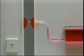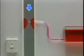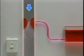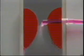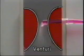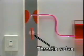Now, let's narrow down the mouth of the tube to speed up the airflow and see what happens when we try it again. As you can see, liquid is atomized, that is, changed into a mist that can be blown out through the pipe. This is basically how a carburetor works. The portion that was made narrower to speed up the airflow is called the venturi. Below the venturi is a throttle valve which controls the air-fuel mixture. It is connected to the accelerator pedal. These comprise the fundamentals of the carburetor.